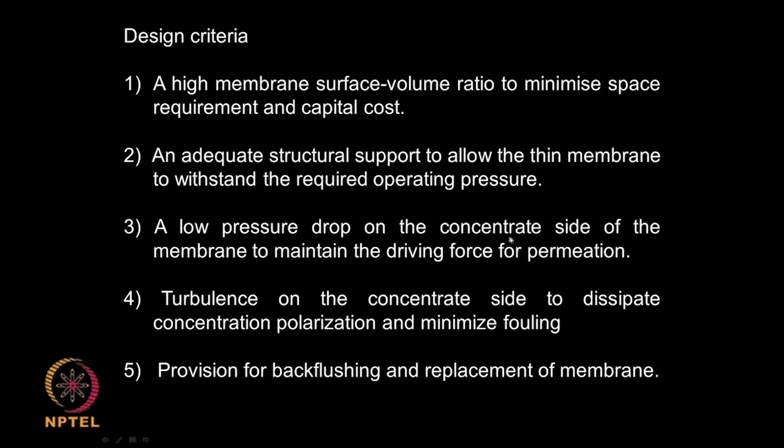A low pressure drop on the concentrate side, so we have enough driving force for permeation. Turbulence on the upstream side, so that there is no concentration polarization and fouling is minimized. Provision for back flushing, so that whatever scales are formed can be removed, and then also we should have the option to replace the membrane.